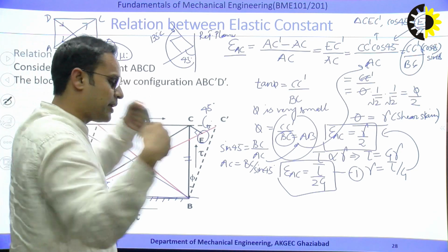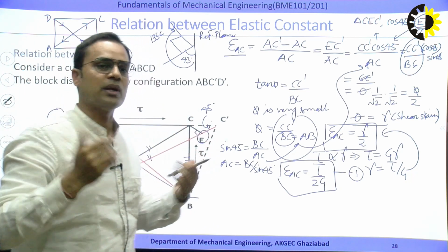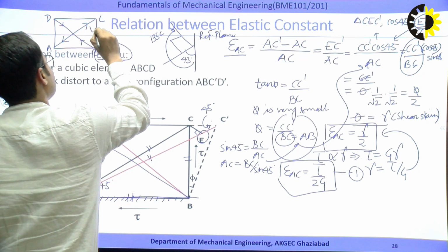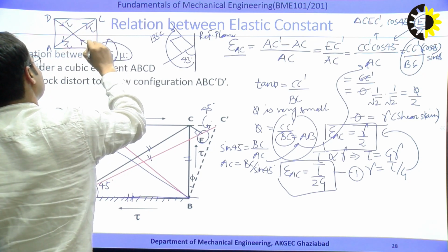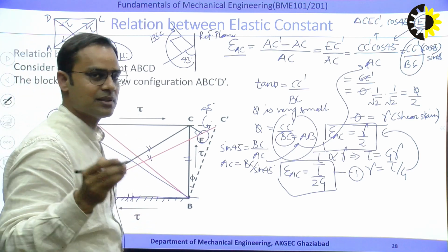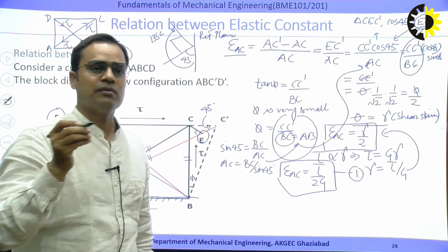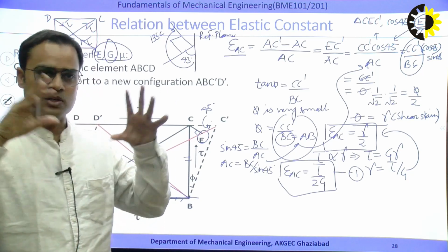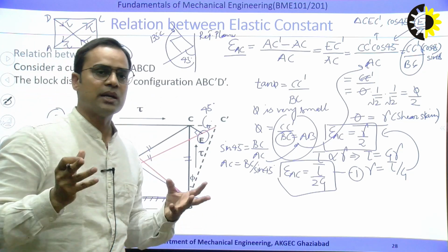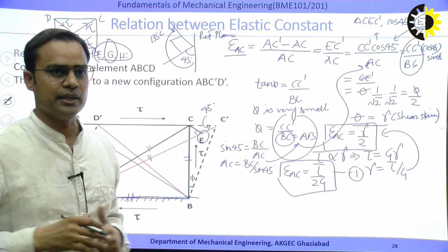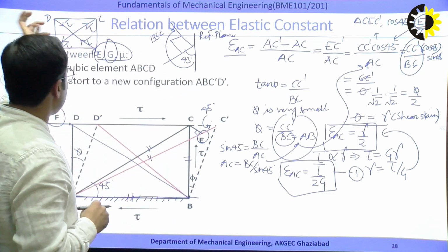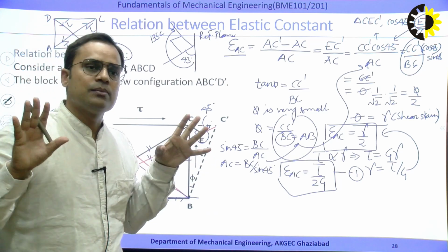The meaning of compressive stress is length is shortened, and the magnitude of these stresses is the same as the shear stress. There is a derivation for that, you can also reference that from any book, but we are not interested here to develop the relation for the pure shear case. We are interested to develop the relation between the elastic constants. That's why I am not going in that direction. So the magnitude is equal to the shear stress.